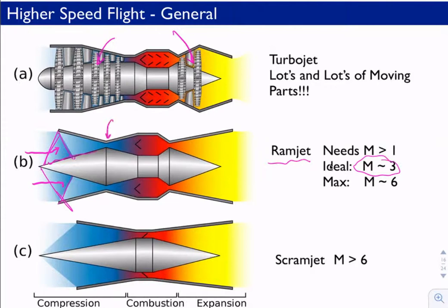So you see this is a converging nozzle, so it's supersonic here, and it's subsonic here. The flow goes through this converging section as supersonic flow, which means it's slowing down, and passes through a throat. Now it is subsonic, and the combustion can be performed on the subsonic fluid because it's tricky to make fluid combust if it's moving too rapidly. And so these engines take advantage of the ability to compress using shock waves, getting the compression rise you need using shock waves, but with subsonic flow in the actual combustion chamber, and producing this net thrust without any moving parts at all.